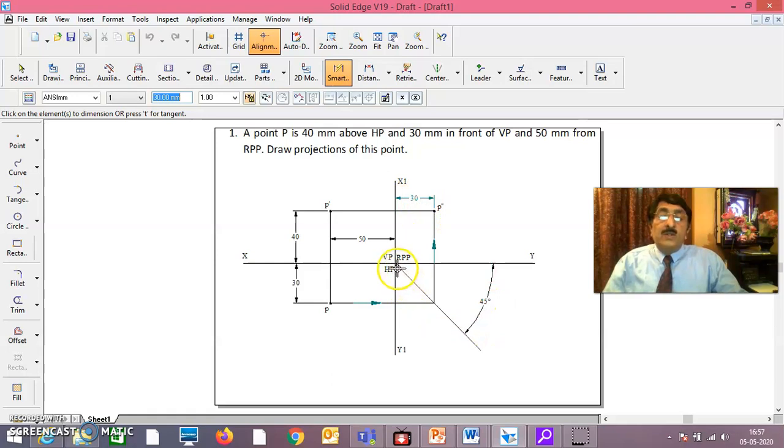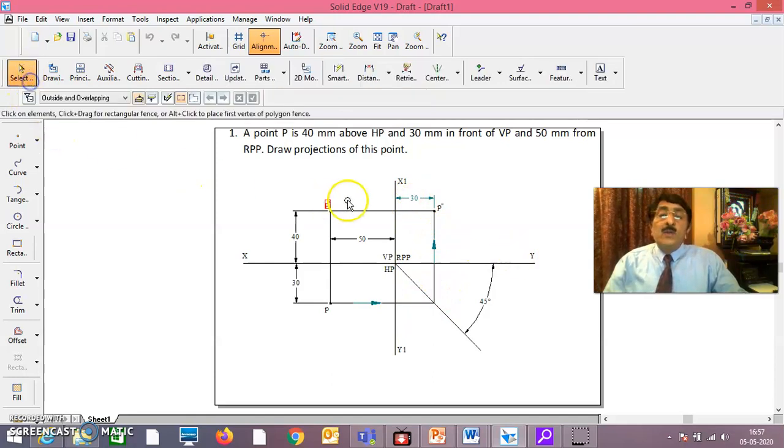That is why what I'll do now, if you do 45-degree line here, it will create a square. This is 30 means this will also be 30. And once this is 30, this will also be 30 because it's a 45-degree line. It creates an imaginary square here. In that way, if this is 30, since it is an imaginary square, automatically this will also be 30 and this will also be 30. In that way, you don't have to show this. This you can eliminate because automatically it will be 30. Okay.